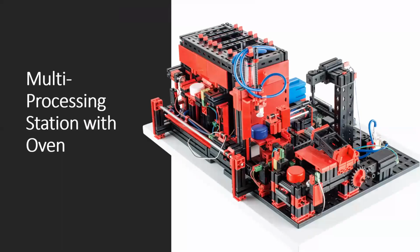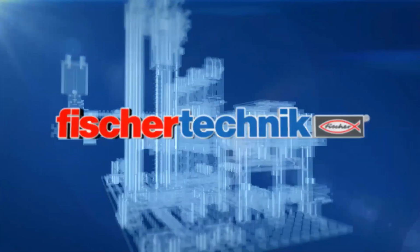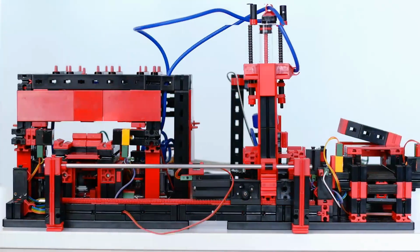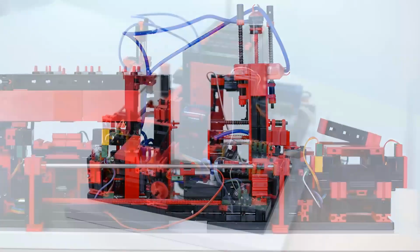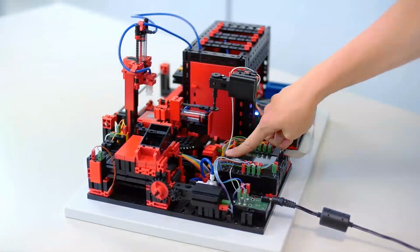The next model in line is the multi-processing station with oven. This model features a furnace simulation with a pneumatic sliding door, as you'll see in just a second. There's a downstream processing station with a pneumatic transfer unit, which includes a vacuum gripper, a cutter with a rotary table, and a conveyor belt. Components used on this model include 4 mini motors, 6 push-button limit switches, 2 phototransistors, 2 LED light barriers, 4 solenoid valves, and a compressor.